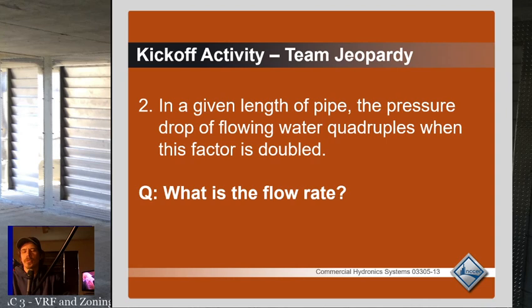So generally when we're sizing boiler piping, we're keeping the velocity... It's everything. Pretty much everything, you have to take velocity into account, how fast the water is moving. You have to take into account how fast the water is moving along in the piping, because based on the size of the piping. I like to bring it up when I'm talking about ductwork, right? Because you have the square foot area of the duct, and then you have how fast the air is moving in the duct in feet per minute, and that gives you cubic feet per minute. You've got 2 dimensions from the duct and 1 dimension on how fast it's moving. It's the same with water.